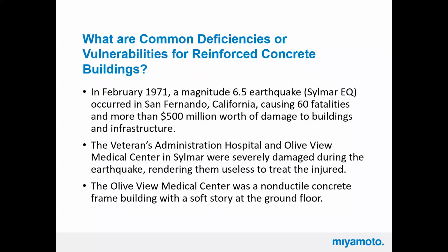And a lot of times it's also valuable, in that last bullet point, to get a geotechnical engineer involved, so we understand, one, the site's seismology and the soil type, and two, if we're going to have to design new foundation elements, we want to look at those with the perspective that we're evaluating an existing building that's been there for a number of years, and maybe not looking at design parameters based on a new building that's going to have a lot of settlement at initial construction. So there's a lot of things to think about when doing seismic evaluation.